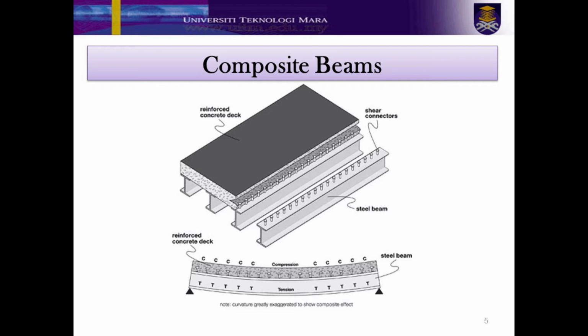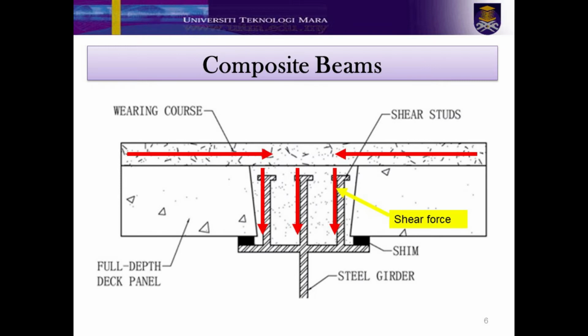This is done using shear connectors fixed to the steel beams and then embedded in the concrete. Shear connectors can be welded on, perhaps using a stud welder, or better still on export work, by fixing nuts and bolts. The shear forces are generally transferred by the use of headed shear studs, or stud connectors.